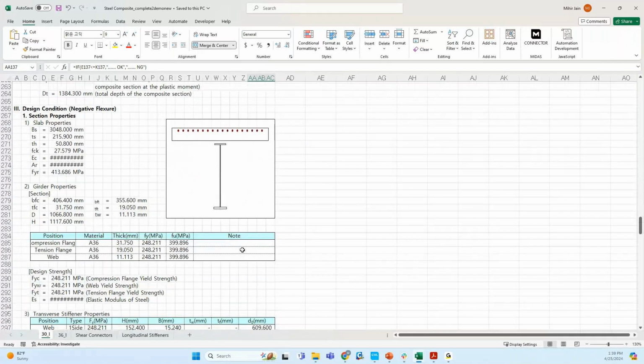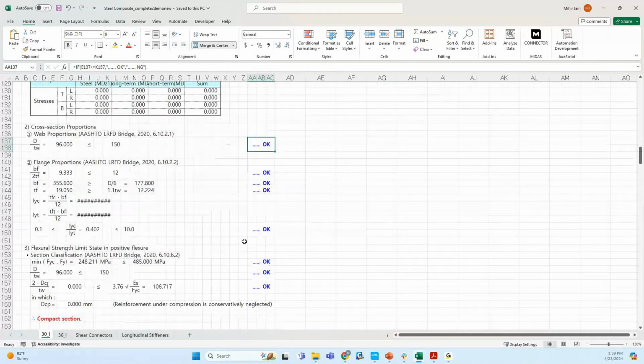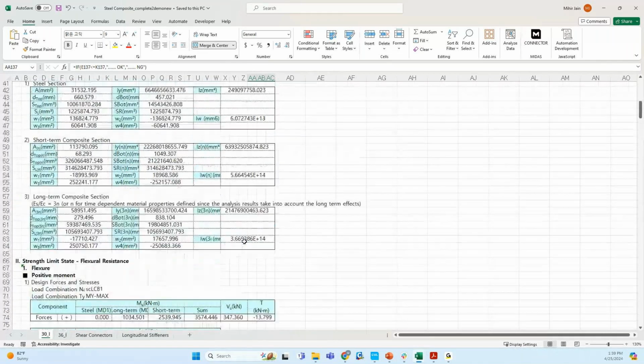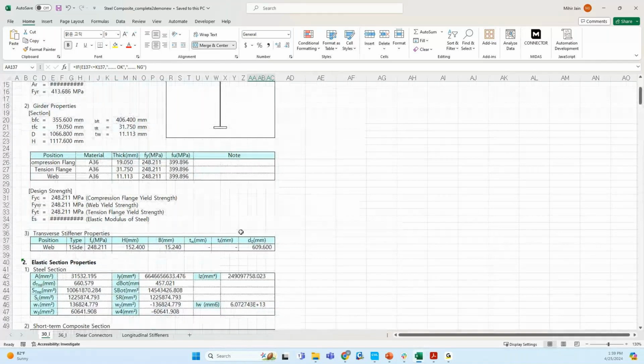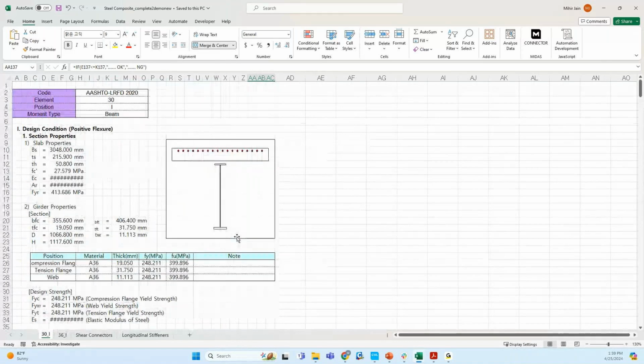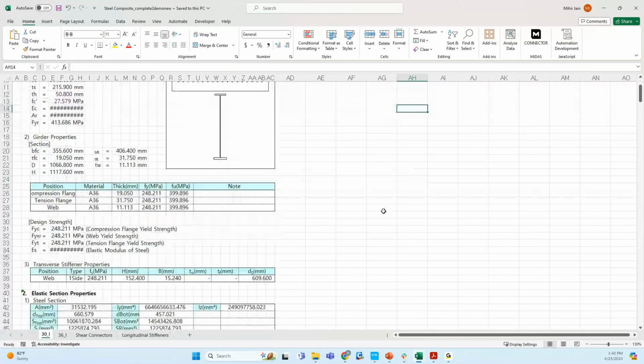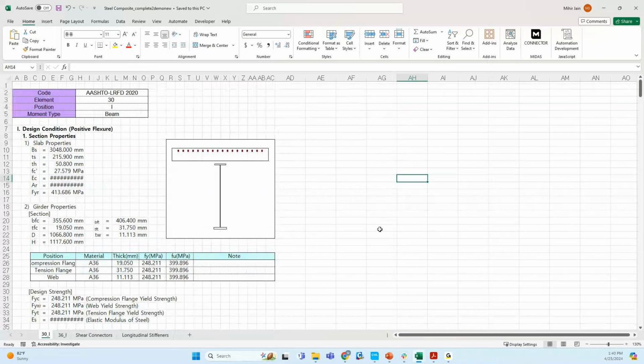Now, an important thing with this is that as of now, this is a standard report as per AASHTO LRFD. But as we know, a lot of DOTs or some states have their own amendments, like Caltrans or Pennsylvania. So the idea here is even if you want to supersede any of the clauses from AASHTO, you get this design report, and parallelly you can have more clauses that supersede some initially created clauses from the LRFD. So it will be easier for you to cross check and upgrade this design report as per your criteria. And that is something that can be automated as well, with the Midas API feature that I'll be describing in the coming webinar as well.